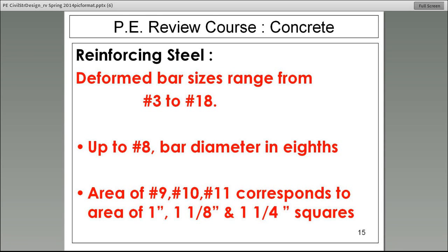However, and guys, please pay attention to the next thing I'm telling you. For that steel to really be helpful to us, we need to place it, where do you think? You got it, on the tension side of the concrete. So we need to look at the beam, look at the dimension, and decide where, top or bottom, right or left, which section of this concrete element is going to be in tension, and that is where you need to place the steel.